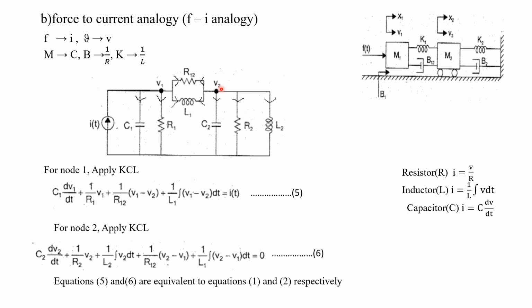While drawing the components which belong only to M2, we have to connect them between the corresponding node and the ground node. All these are related only to mass M2. Now what we have to do is find the elements connected between M2 as well as M1. K1 is nothing but L1, so this is already connected. No need to connect it again.